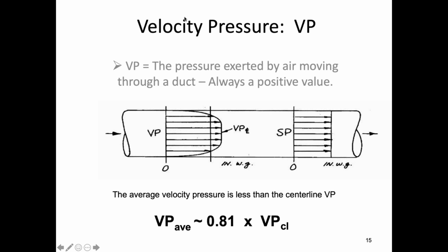So basically you're measuring the total pressure, and then put this on the other side of the manometer and you subtract the static pressure. So this hooked up in the right way on a manometer is going to give you the velocity pressure, but only because it's measuring both at the same time. A little tricky, right? So this is one of the basic devices for measuring velocity pressure.